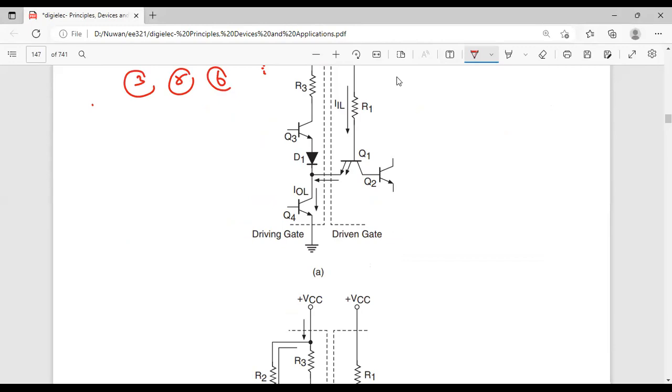Anyway, let's say it is 6-bit. You have to use 6 bits for the ADC output. That means 6 bits will represent one voltage level. So there are 2 to the power 6 levels, between 0 and 5 volt.